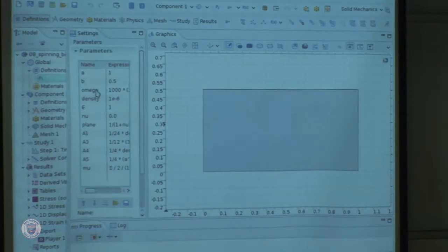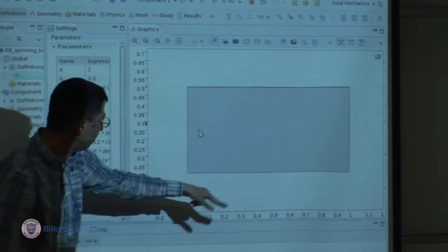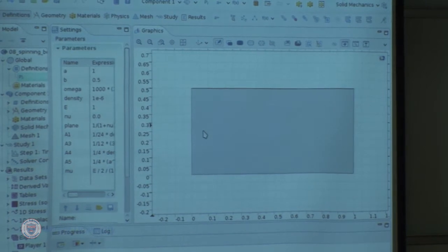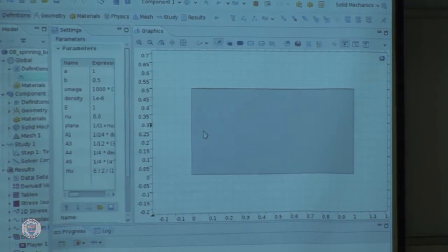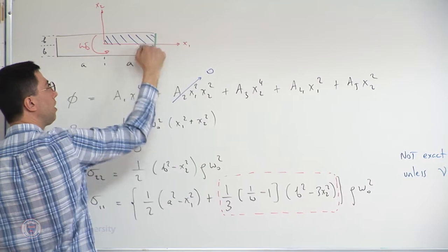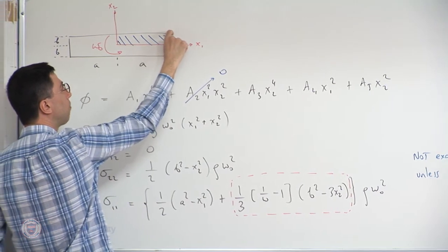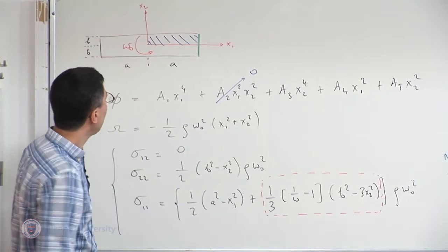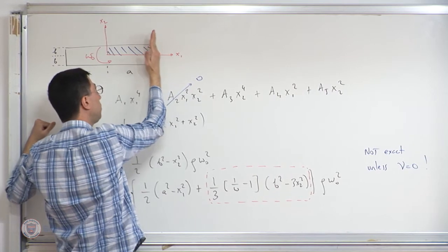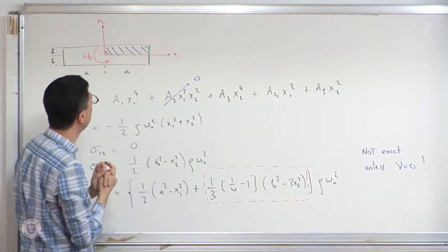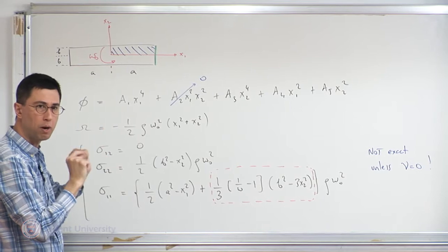Again, I have some angular velocity. Omega naught is the same as in the spinning disk, actually. The width is 1. The height, the B value, is 0.5, so the ratio of B to A is 1/2. It's pretty large. Since I already discussed that there will be some end effects due to the integral formulation of this boundary, the relaxation of the boundary condition, and that the end effects will be of order B, I expect that the larger B is, the more the end effects introduced by my approximation will diffuse into my domain. Conversely, the smaller the height B is, the better my approximation will be.